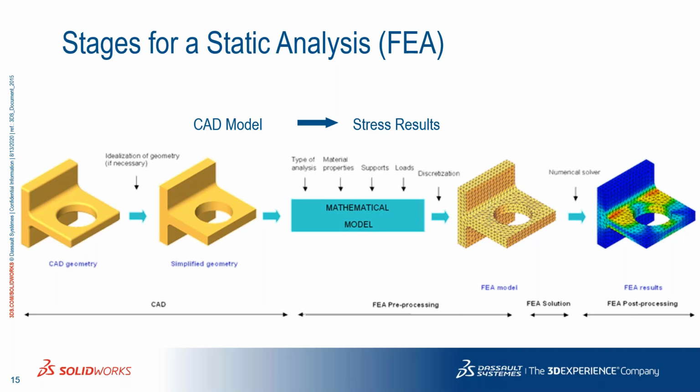Now after this, we will have the solver. Using the formulas, it is going to calculate the stresses acting, the displacements, as well as the strain in your model. You can see the results in the form of FEA plots, where we can identify where the stresses are maximum, where the displacement is maximum, and where the strain is maximum.